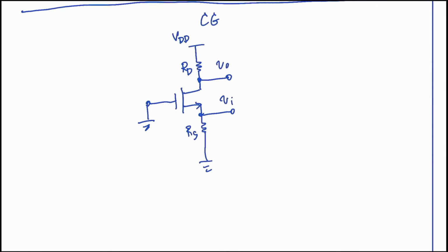Normally, if we were to draw out the entire DC bias circuit for this configuration, we would usually bias it in this specific way, and then connect an R2 resistor right here. You might be wondering, how exactly is the gate pin made to go to ground in this setup? Well, it is accomplished by using another capacitor which is connected to ground in this manner, effectively providing a path for the signal while maintaining the DC bias conditions.